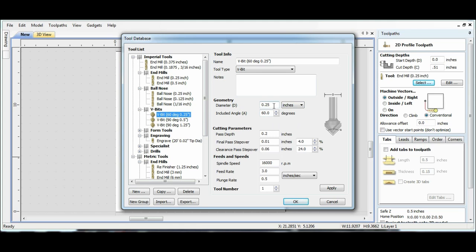With a V groove bit, you can have the diameter of the shank, but the machine does not care at all. So it's just the cutter. It's just the cutter, absolutely. With our machine, I don't really see why any machine would need to know the diameter of the shank. It needs to know the diameter of the actual cutting bit, because just like this V-groove bit here, the actual cutting head's diameter is way wider than the shank. The shank is just the long part of the router bit, and those come in 1/8 inch, 1/4 inch, 3/8, and so on. Once again, the machine does not care about the diameter of the shank. It does care about the diameter of the cutter head. So when you see diameter within this prompt, it's talking about the cutter head.